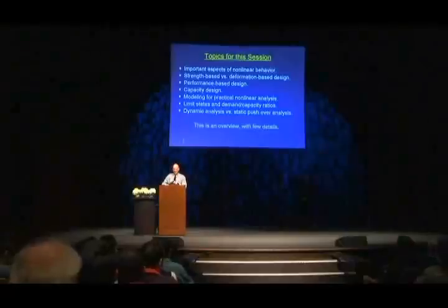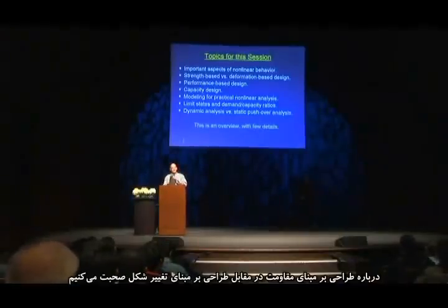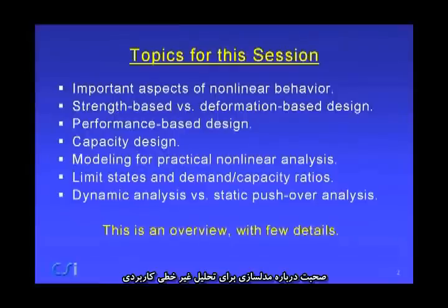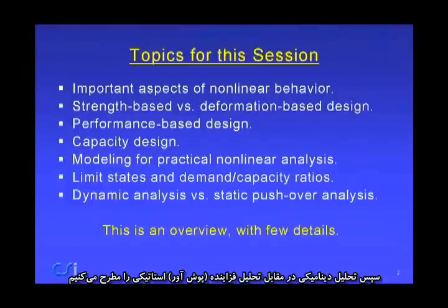Topics for this session are as follows. The important aspects of nonlinear behavior. I'll touch on strength-based versus deformation-based design, performance-based design, capacity design, talk about modeling for practical nonlinear analysis, some limit states and demand capacity ratios, and then dynamic analysis versus static pushover analysis.